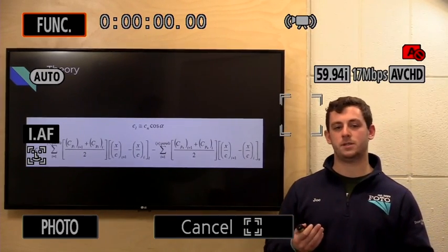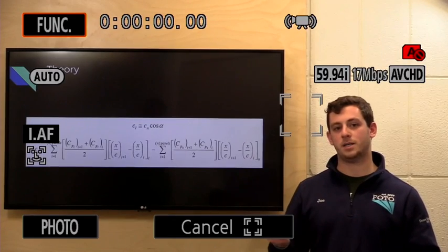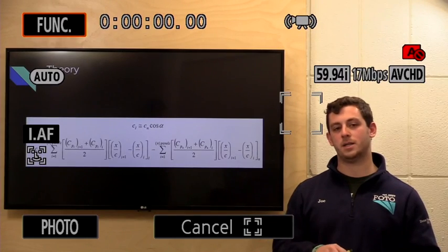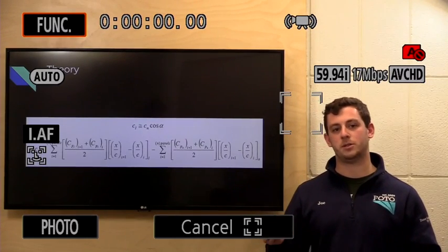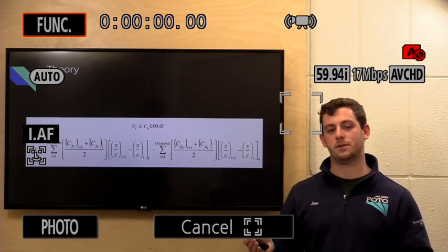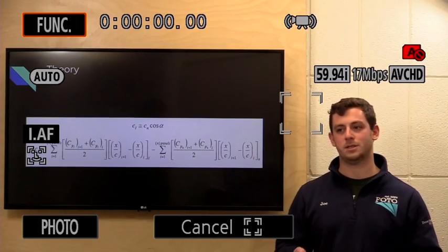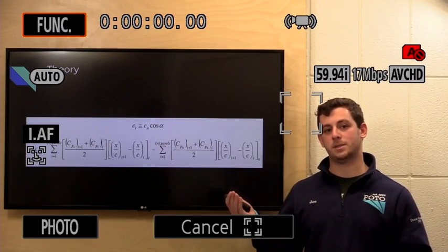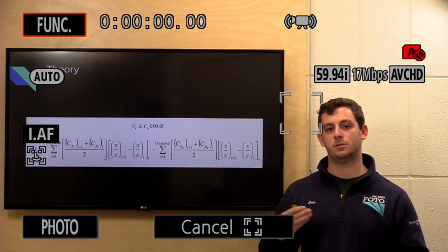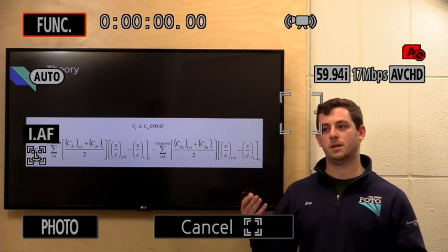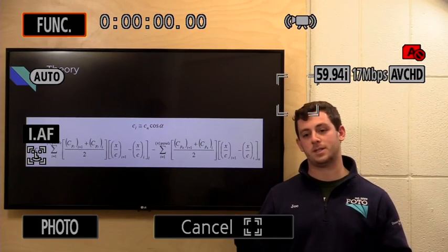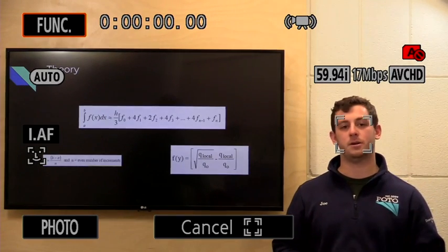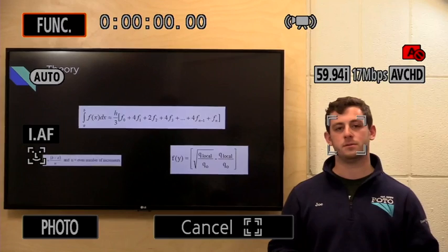So into this normal coefficient, it's important to note that if it is positive, that means we have positive lift, and that in order for it to be positive, we have to have lower pressure coefficients across the upper surface of our airfoil as opposed to the lower surface to generate this lift. And it is important also to note that the angle of attack comes into account here as well, so that it's not just the normal coefficient, but the normal coefficient by the cosine of our angle of attack that actually generates the lift. So in order to calculate the drag coefficients on our airfoil, we have to use Simpson's rule.